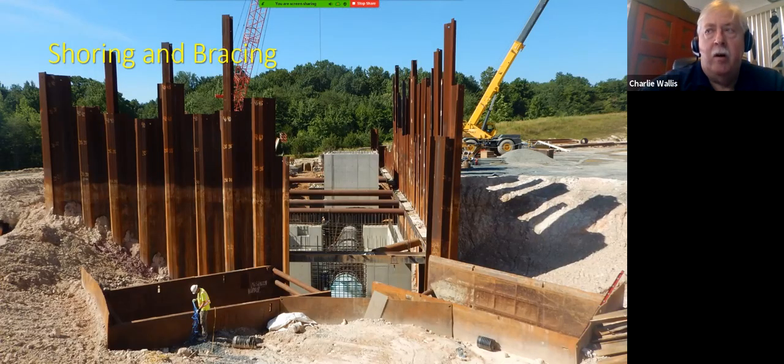Sometimes excavations occur at the foot of a dam, and shoring and bracing is required. In this case, this is what sheet piling looks like. This is placed, the work can be performed, and then the piling can be removed.